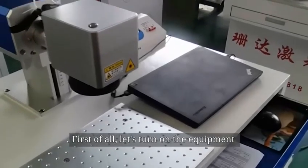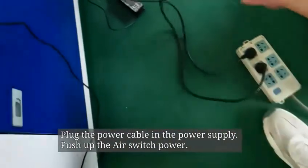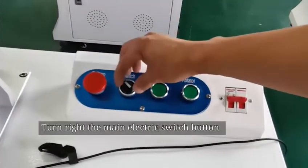First of all, let's turn on the equipment. Plug the power cable into the power supply. Push up the air switch power. Turn right the emergency stop button to release it. Turn right the main electric switch button.